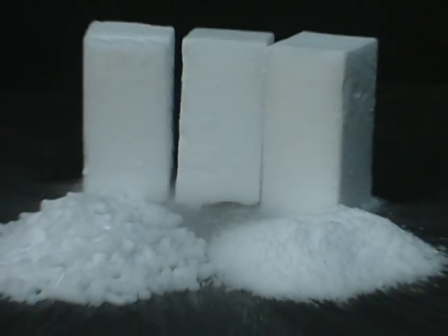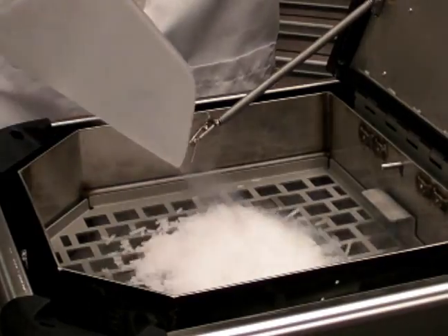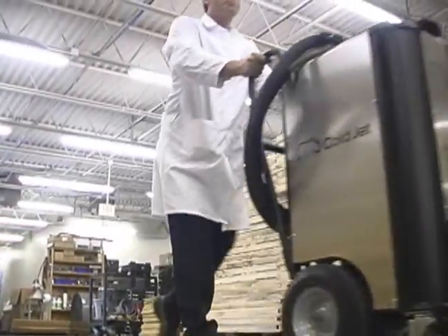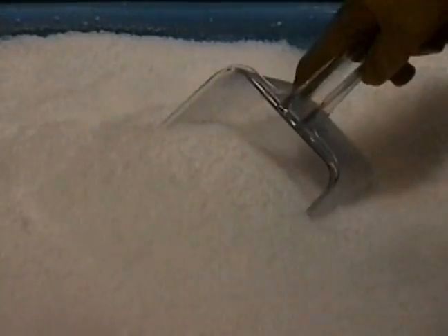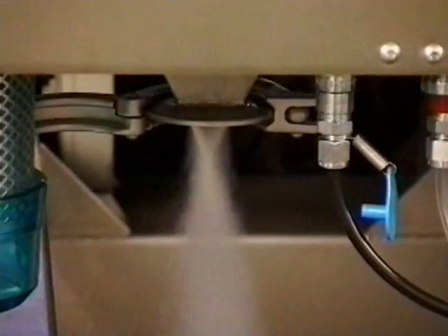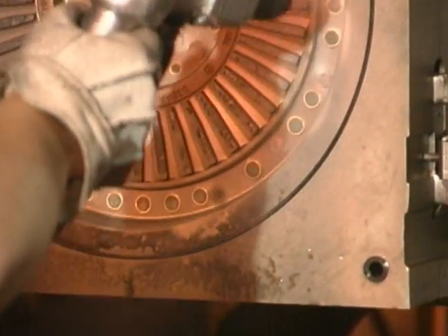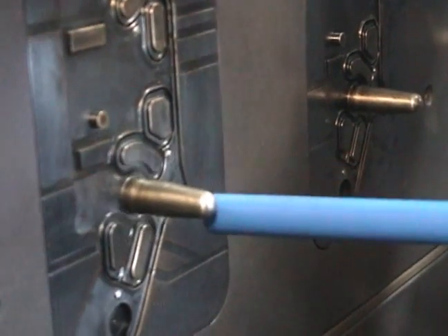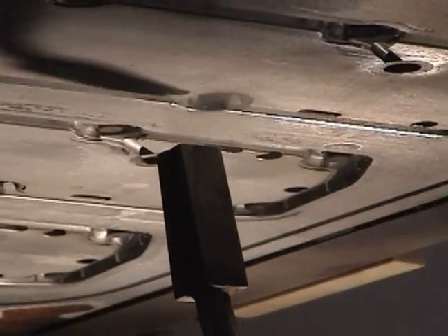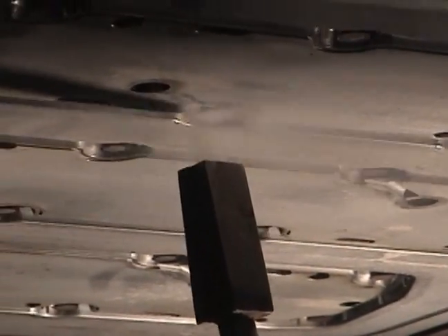Dry ice is generally available in three forms. Most dry ice blasting units require the use of rice-sized pellets. We are the only company to offer blasting units capable of using any form of dry ice, whether it be pellets, block, or nuggets. Not only are these smaller crystals more effective than the larger pellets in cleaning equipment with intricate surfaces or tiny openings such as screens or microvents, but they also provide about 1,000 times more surface strikes for a given volume of ice. This provides more thorough surface coverage, leading to faster removal rates on thinner contaminants.